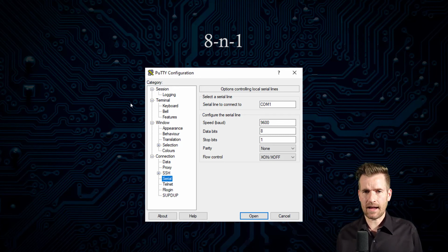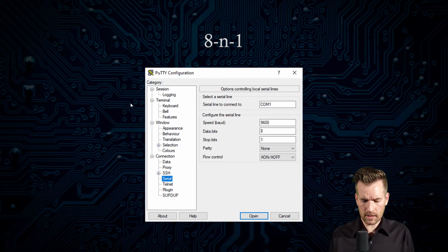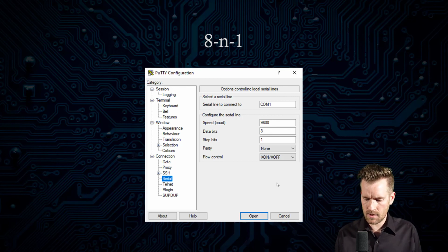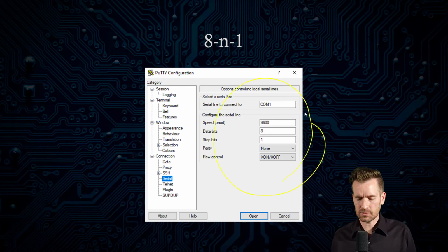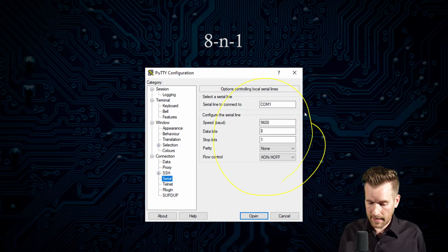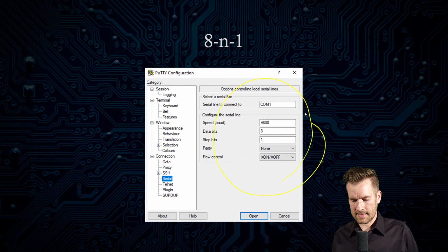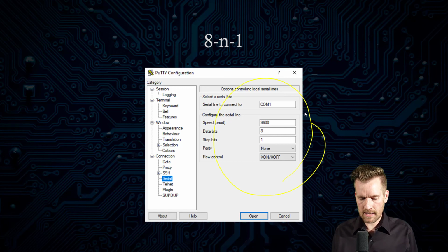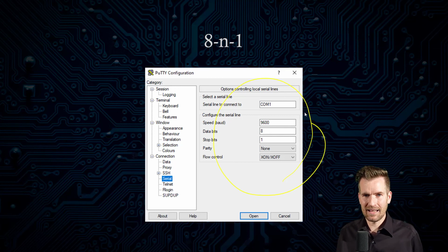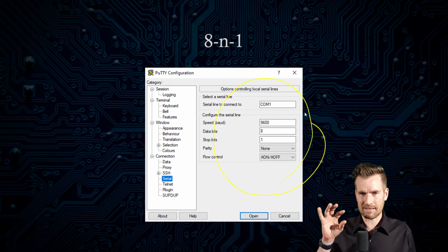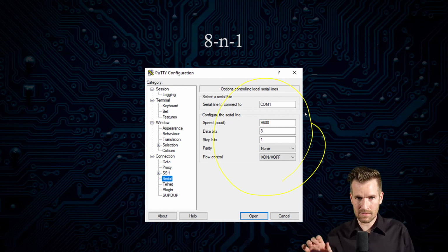Once we select that we want to connect via the serial cable, we can go down to the serial settings and actually see where these settings play out. We see that this is set to a baud rate of 9600, that it has 8 data bits, and it has a stop bit. There is no parity, and the flow control is XON/XOFF. These are the settings, and it's interesting: if you get these settings wrong in here, then what you'll see up on your screen is just garbled, like something from the Matrix, incomprehensible as to what it's displaying.